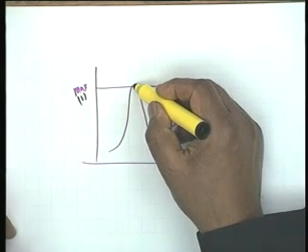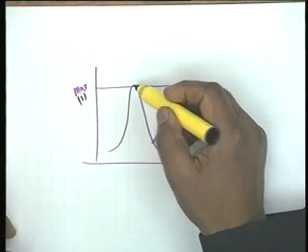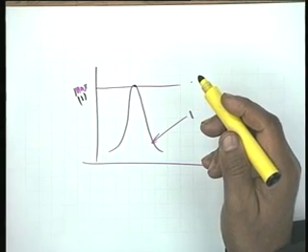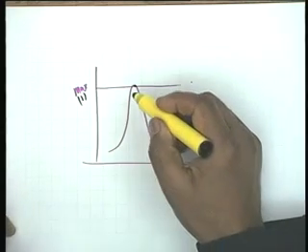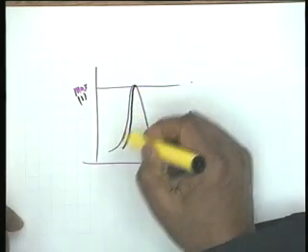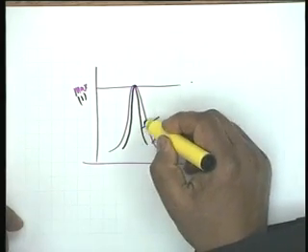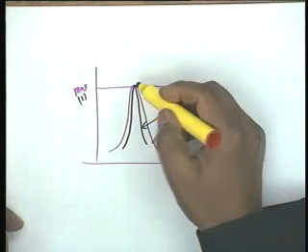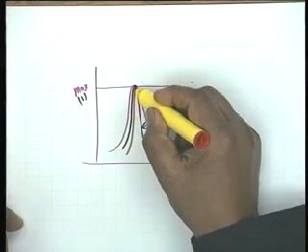Then you see the maximum does not change, but at any other frequency away from the maximum, 0.9 squared is 0.81, and therefore it becomes sharper. So, with two such circuits I shall get a sharper response, and if I connect another circuit now, I will get still sharper.